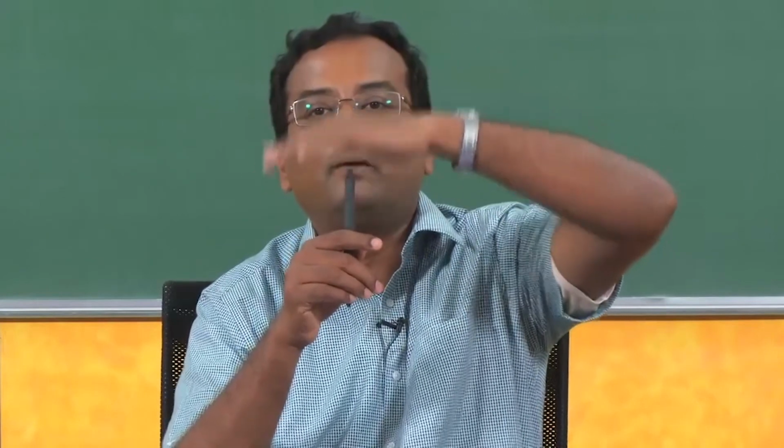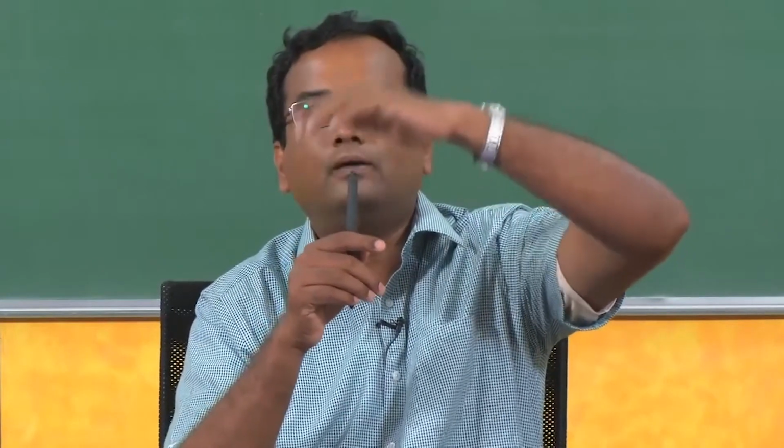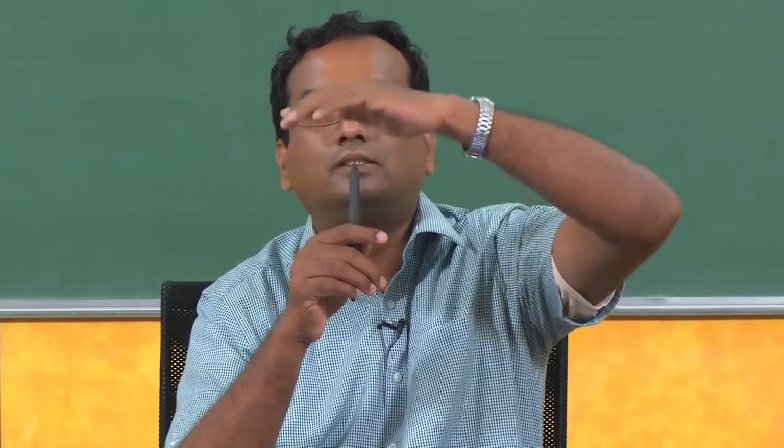So, this is basically going to produce a shear, sigma xy shear. This sliding is going to provide a sigma xy shear, because x is along this direction of the force, y is perpendicular to the web surface on which this flange is moving. This produces a sigma xy shear stress. So, the web has to be designed, the weld has to be designed for sigma xy shear stress.